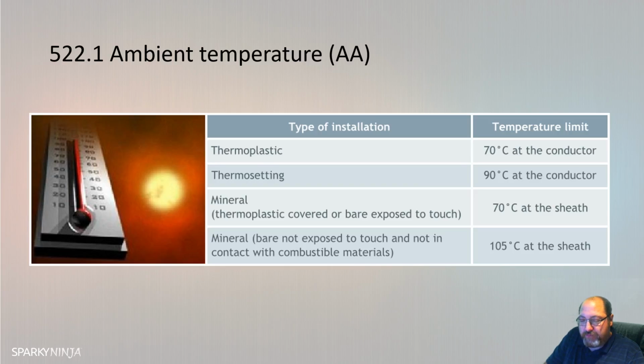If we get down to, for example, water, AD, you can see that there are then negligible, AD1, drops, AD2, sprays, AD3, splashes, AD4. When we think of water, though, we don't think of AD, we think of IP ratings. But this is the external influence category. This will then refer you to an IP rating, and you can see that if you turn into the actual guidance that's with this appendix.